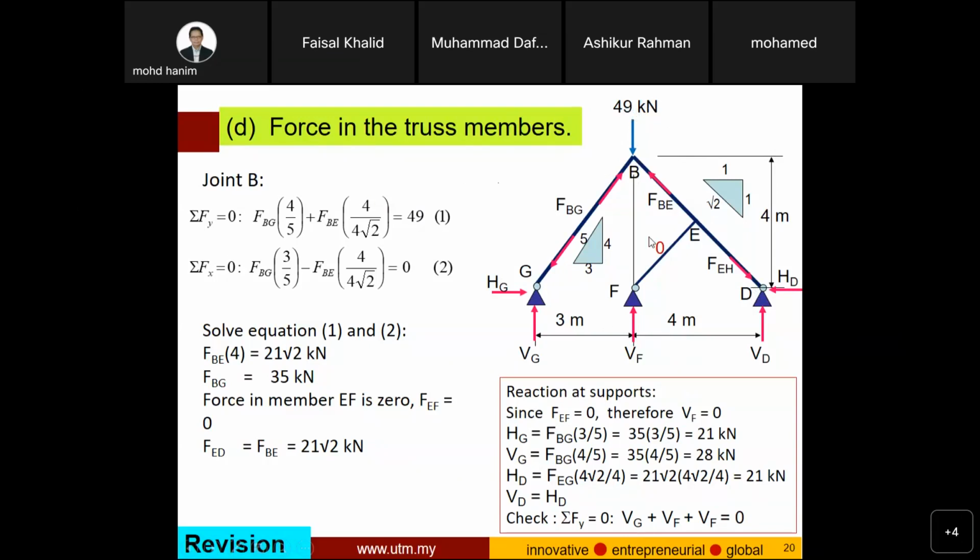Okay, about this truss system, how many reactions? 1, 2, 3, 4, 5. It looks like this is externally indeterminate. Even though the number of reactions, 5, is more than 3, in this case the force in the members can still be calculated.